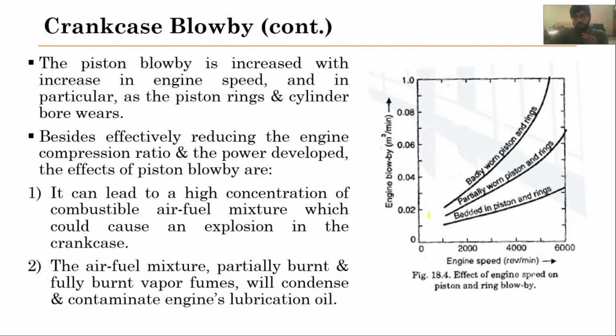From this graph, we can see that when we have bedded-in pistons and rings, we have lesser blow-by losses, and when the RPMs are increasing, these blow-by losses are also increasing. But again, in bedded-in pistons and rings we have lesser blow-by losses, while in partially worn rings or badly worn pistons and rings, these losses are increasing quite significantly.